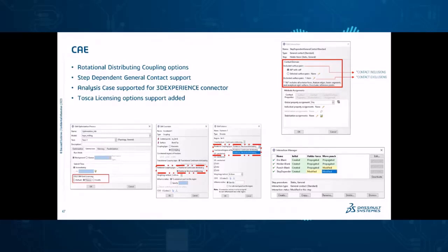We've added support for requesting P-force, contact force, which is the nodal force vector for fluid pressure penetration loading. There is also support for star contact mass scaling for explicit, and you can specify the surfaces for the contact mass scaling.